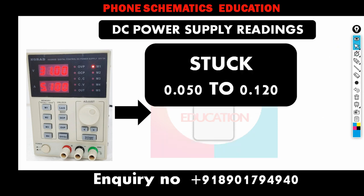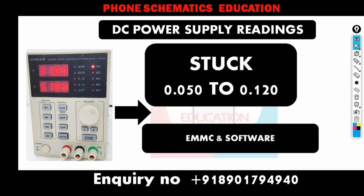Now, stuck. When you connect the DC power supply, no consumption. When you try to press the button or on off button, it takes 50 to 120. Let's suppose in some phone the reading is stuck at 70, or stuck at 80, or stuck at 85. These types of issues you all must have noticed, right? Then the problem comes from the storage IC called MMC or UFS, right?